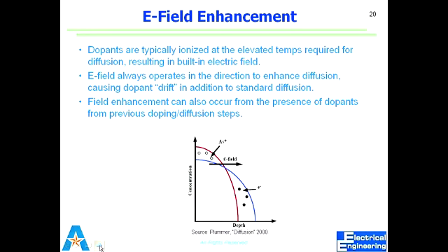Diffusion is related with concentration, high concentration. Both are movement of charge. One is against an applied field, the other is not. So drift is what happens when you apply a field, when you bias, when you put some batteries around. Then charge flows. So drift is movement of charge in a field. When you have positive bias and negative bias, they travel towards opposite electrodes. Negative charges go to positive.